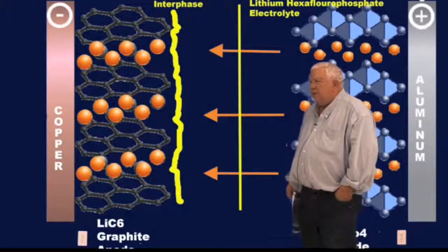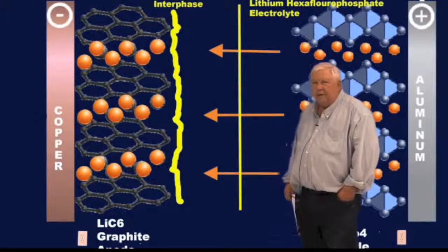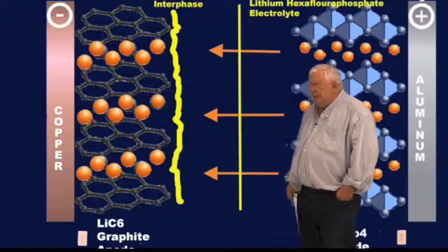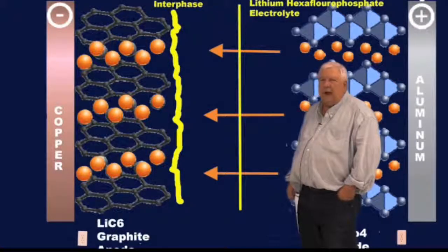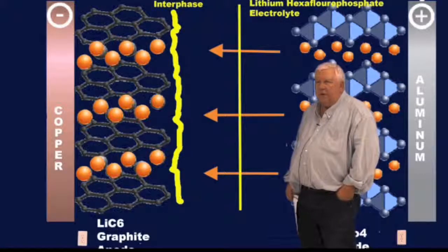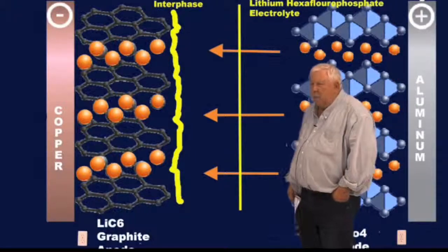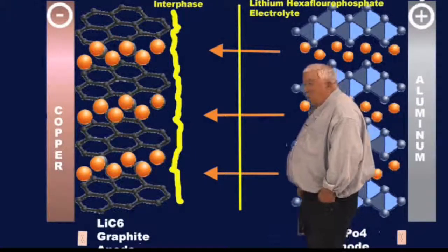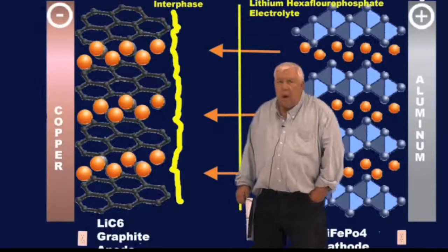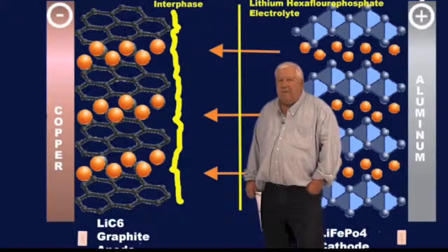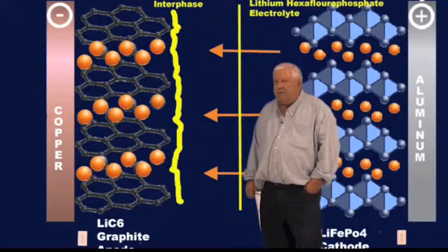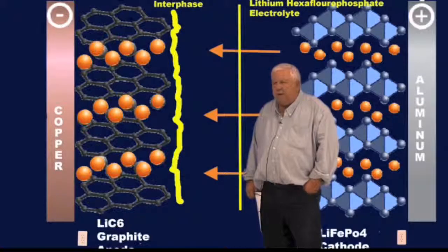That gets you into whether the 120 or 130 degrees in the Phoenix parking lot can shorten the life of the cell. Probably not measurably, probably not in any practical sense. It certainly has an effect, but the effect would most likely be so small that you would need fairly sophisticated equipment to be able to detect it across, say, 5 years. But temperature does have an effect. We like to talk about all things with lithium batteries below 60 degrees centigrade, 158 degrees Fahrenheit.